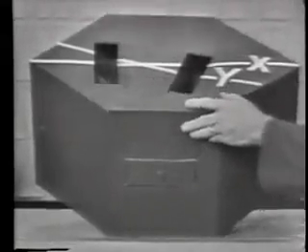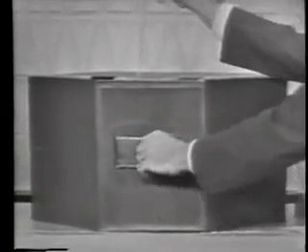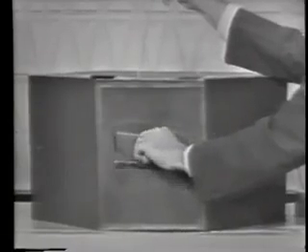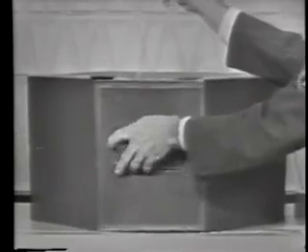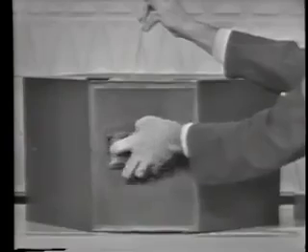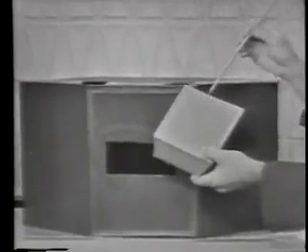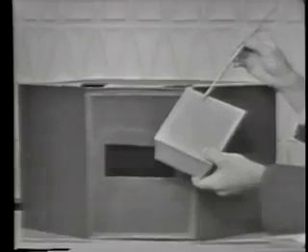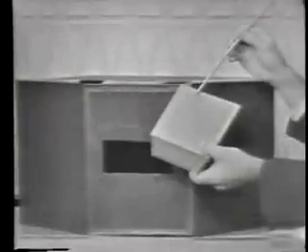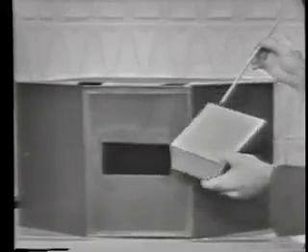Now, in this case, the crystal cut is taken right in, or made right into the face of the crystal. Remember, the z-axis is running down through the crystal in this manner. And we'll cut at a 35-degree angle from this z-axis. And removing the cut from the crystal, again, only a small portion of the natural crystal, we call this cut an AT cut. An AT cut crystal. Okay, let's go back to our chart once more, and I want you to complete item 4 in the TVI guide.